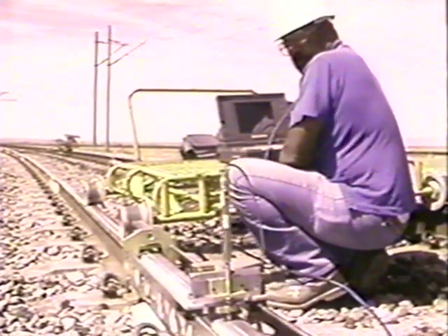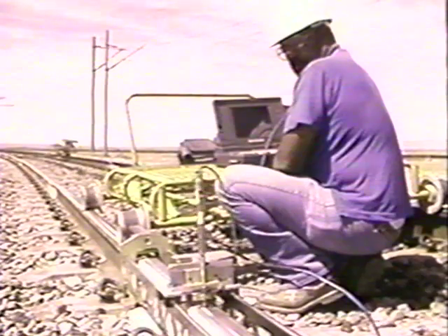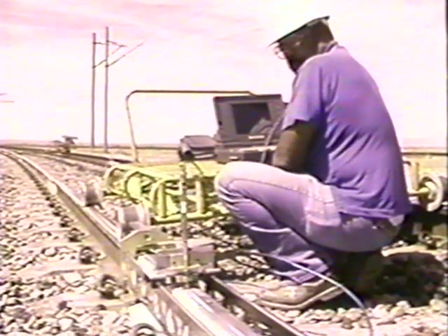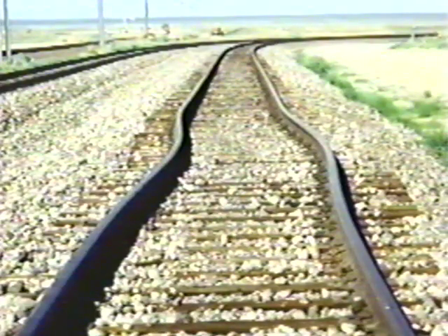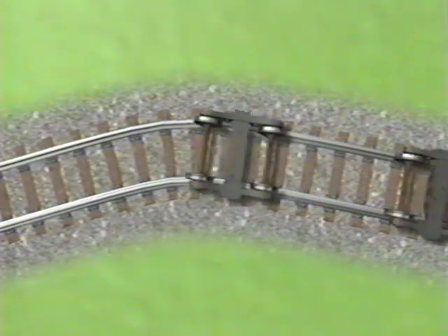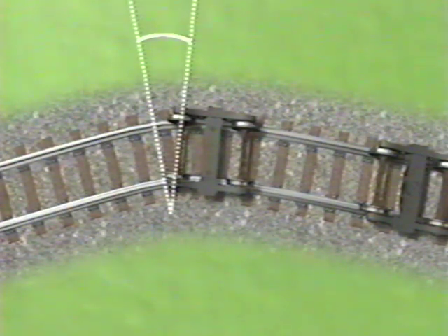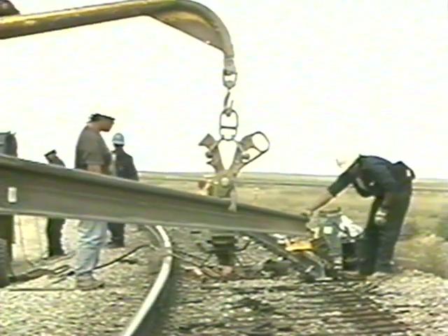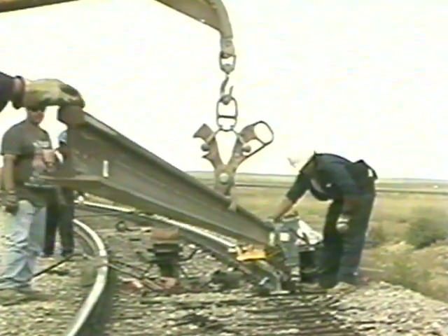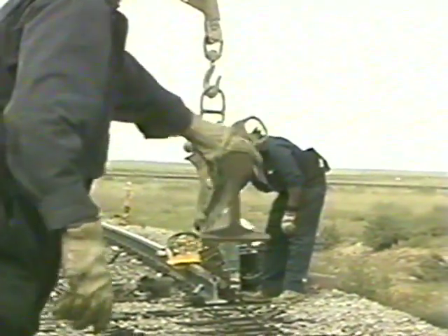Another factor that can increase the angle of attack of the wheel set is track alignment. Flange climb derailments are often associated with track that has an alignment kink. The rapid increase in curvature at the kink makes it difficult for railcar trucks to properly align themselves with the track. As a result, the wheel sets can develop large angles of attack. Thus, it is critical to maintain proper track alignment to help reduce the chances of a flange climb derailment.